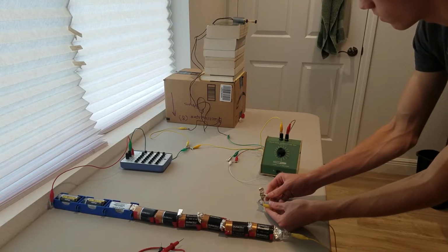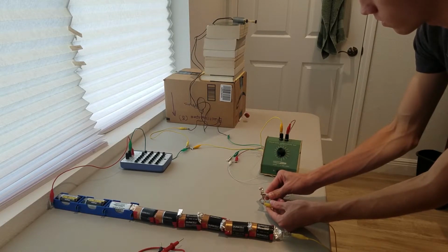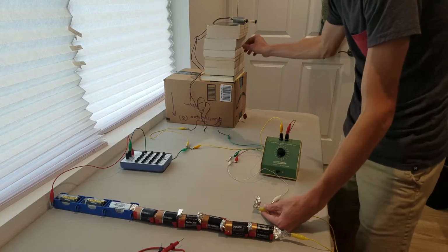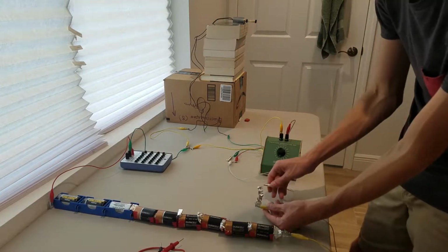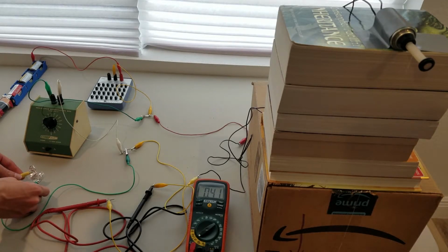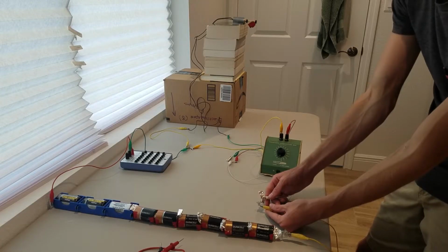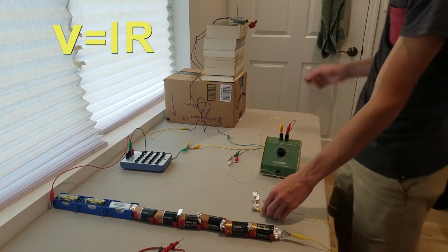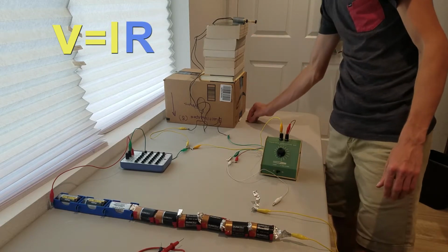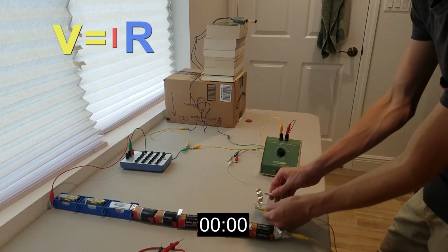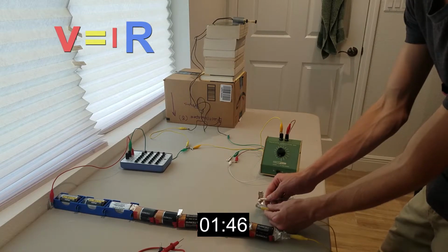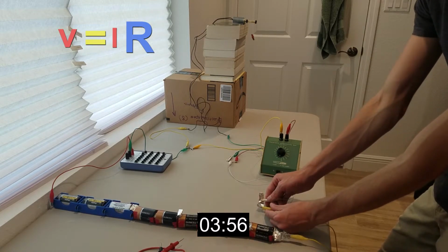When R2 is placed in parallel with the motor, it splits the current going to the motor to now also go through R2. Looking at the multimeter measuring the current through the motor, we can see that the current is a little more than 0.4 amps. Using the same method with Ohm's law as before, the resistance of the motor is constant while the current decreases, meaning the voltage across the motor also decreases, giving a longer time interval as seen above.